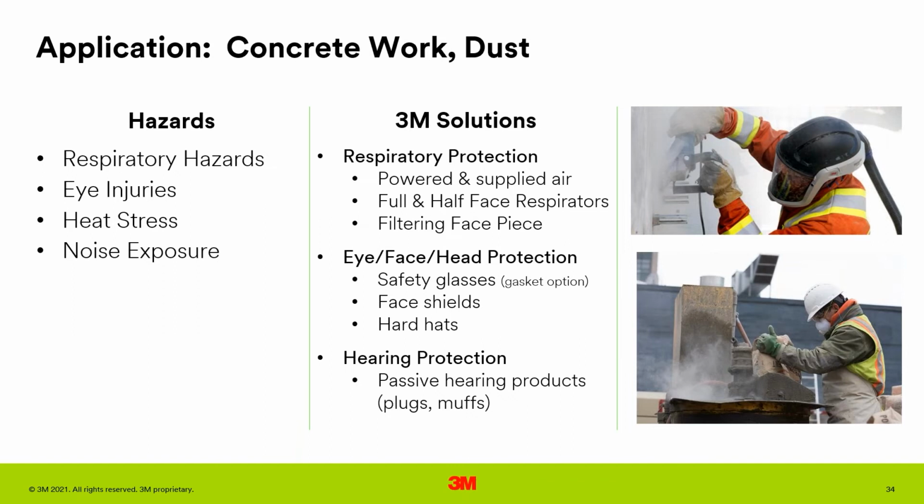So when we talk about silica, we're talking about concrete work and dust. When you're doing concrete work, you have to be concerned about the respiratory hazard of the silica itself, potential eye injuries from flying objects, heat stress from being outside in hot weather, and also the noise exposure from the grinding and other parts of the equipment there.